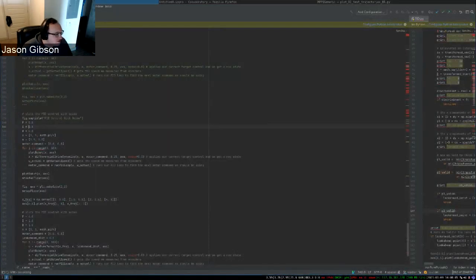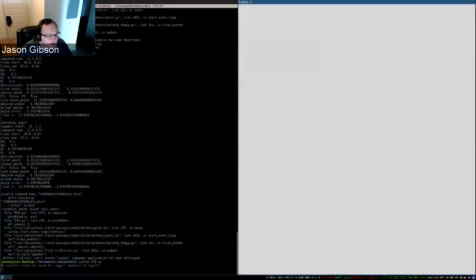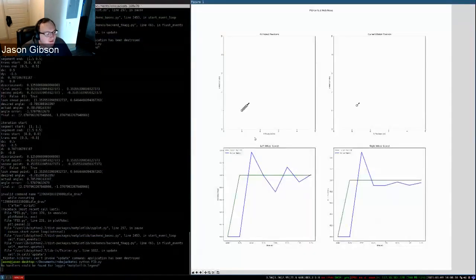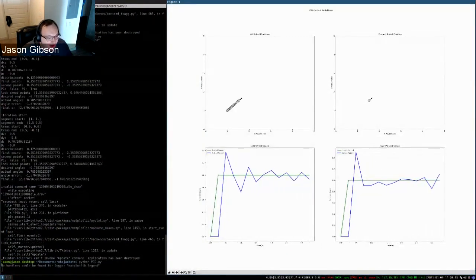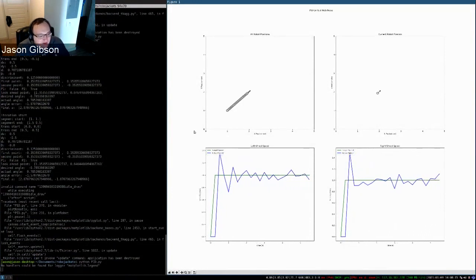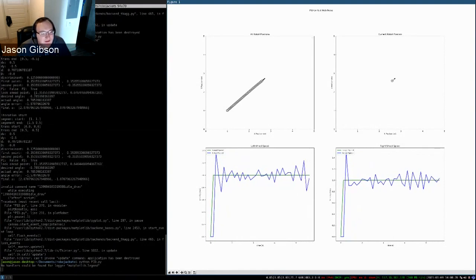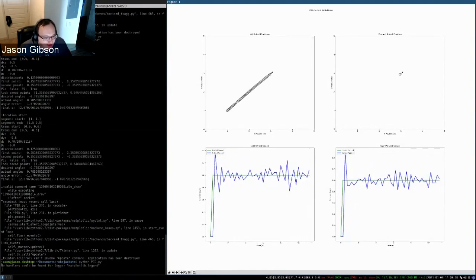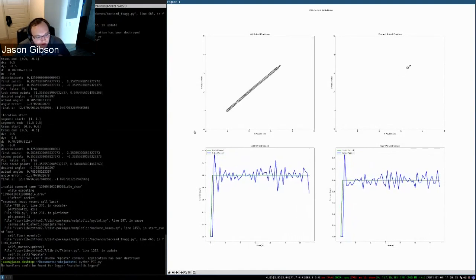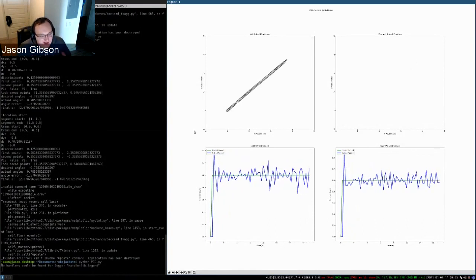So now I'll just use the same constants as before. Now we have this nice PID loop, with an I of 1 and a D of 1. What you can see here is we never actually directly converge the value like we were seeing before, and that's just because the amount of noise I'm adding is kind of ridiculous. We're never going to converge to an actual value, and this is what you'll tend to see in hardware, just because things are always going to happen. The whole point is that PID is compensating for it. As you can see here, this is our line, pretty straight.